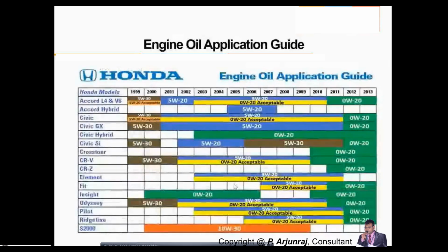This is an example taken from a Honda engine oil application guide. There are different models, like the Honda Accord, Hybrid, Civic, and they use 0W20, and they also use 5W30, but mostly beyond 2013 they are going for 0W20, and now mostly all are 0W20.